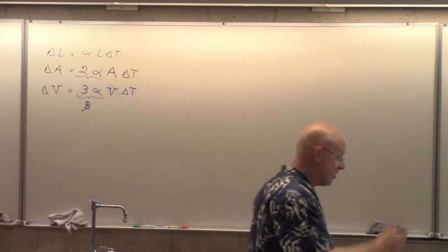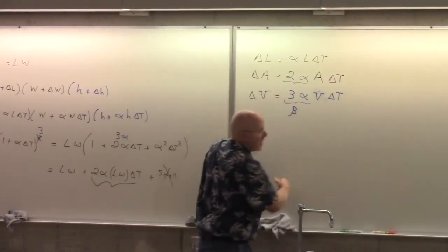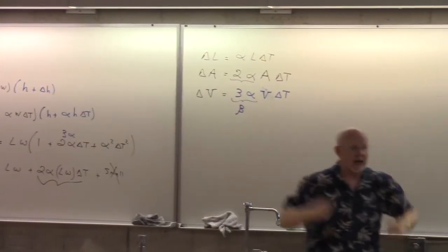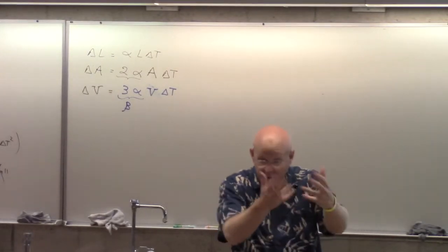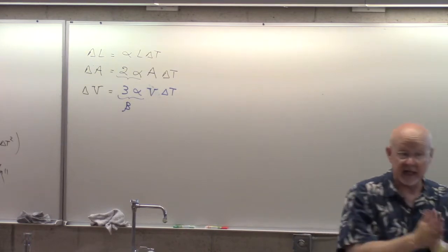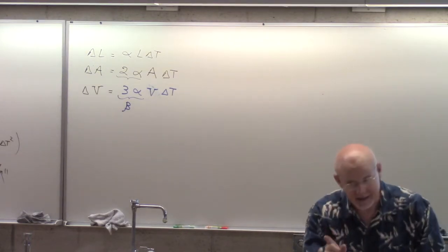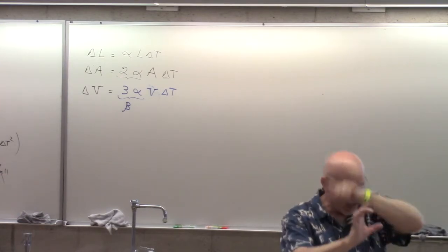Because usually the question I get from the homework is students ask me, hey, when you calculated how much bigger the diameter got, you treated it as if it was made out of brass, but it's a hole. A hole is not made out of brass. And I need to say, well, yes, but the hole is made from the brass around it.